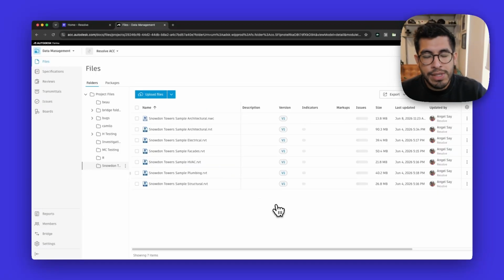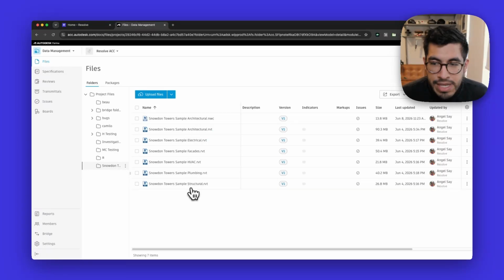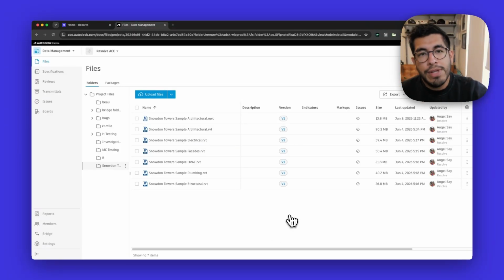And just to show you what this corresponds to on the Autodesk side, these are the files that I just linked to Resolve. These are the individual files that I had hosted. Prior to this, if you wanted to add multiple disciplines into Resolve, they did all need to be in a container file. So you needed to create a Revit file with a view that had everything linked in, or a Navisworks file that you then had to update manually. Maybe not on Resolve because we have the connection to Autodesk, but maybe you did have to bring it into Navisworks manually, then push it to Autodesk Forma, and then it would finally automatically update in Resolve. And that kind of defeats the purpose of the automatic workflow. Now you just select the individual files that you want, and as the versions upgrade automatically on the Autodesk side, they will update in Resolve.